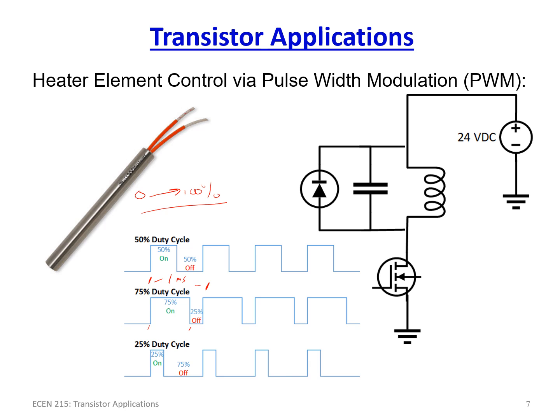DC to AC inverters: if you have a 12-volt battery and you want to generate 120 volts VAC, it actually uses PWM, an H-bridge and a transformer to generate 120 volts. So PWM is heavily used, and it's usually at a pretty high frequency, 20, 30 kilohertz, but in the end, it's all about duty cycle.